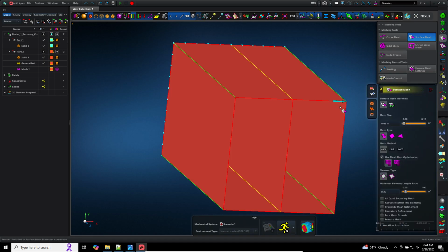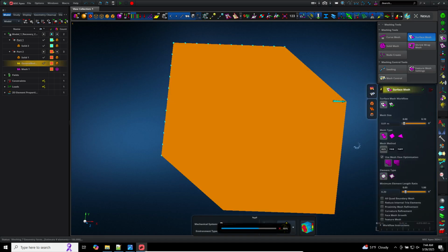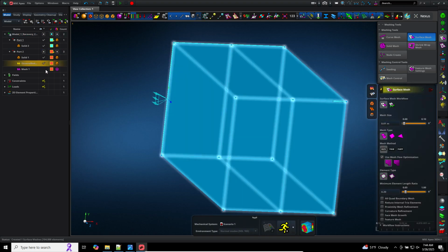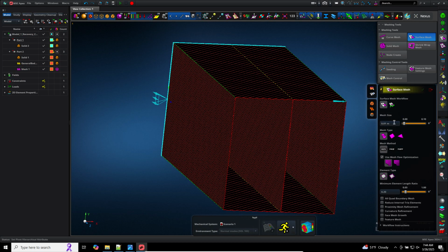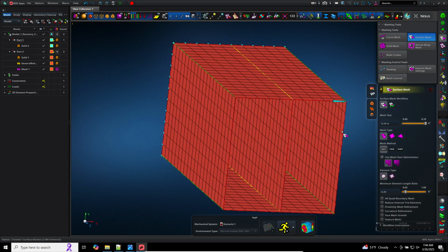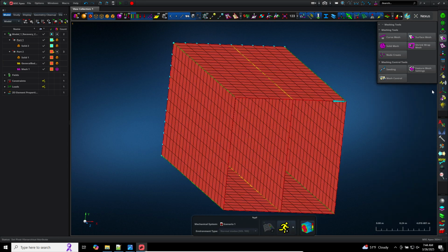So again, a normal modes analysis would be good for debugging. Like I mentioned earlier, there is an engineering purpose for a normal modes analysis, but it's also very useful for debugging a finite element model. It helps you identify whether or not there are detached parts or meshes in your model.